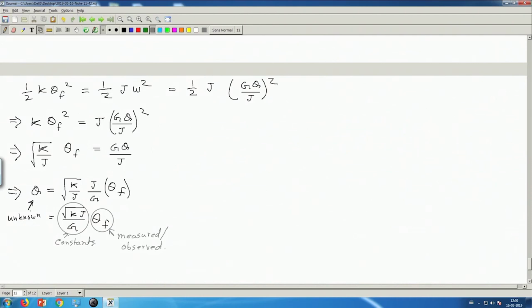Very quickly, let us summarize how we will do it experimentally. We will let the impulse current flow through the coil and then the pointer will start to move and oscillate. Okay. So, if the pointer is initially at its 0 position, and then the impulse current flows, it will set the pointer in motion, it will give it some kinetic energy.